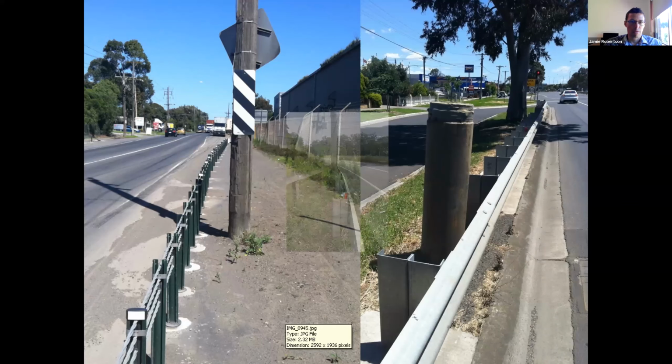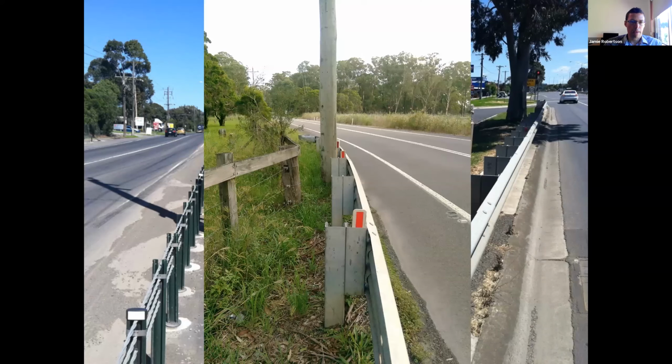That's often not feasible. And here's another case where we've got a power pole that's virtually touching that barrier. It's not a by-the-book design. It would be great if we could do better, but in this case, we've gone with a thrie beam installation. It is on the inside of a curve, so the risk of someone departing the road there is probably reduced. While this is not ideal, I would suggest that it's better than doing nothing. It does afford some protection to that pole.